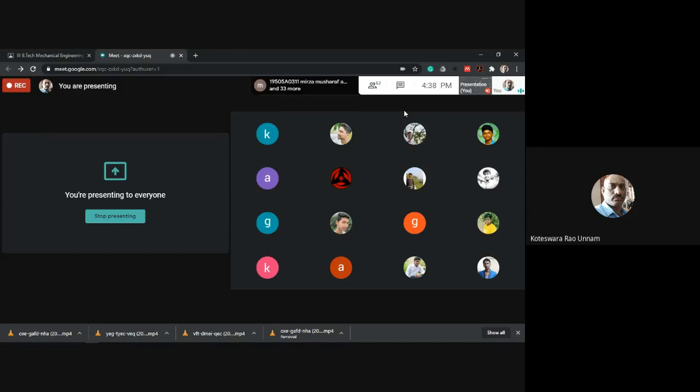Similarly, if I want to go for a butt joint having a specified efficiency, let us say 80%, then I can go for triple riveted equal width straps, or triple riveted unequal width straps also. So you need to first decide what type of joint you need to use. Then, based on the joint, you need to design it, meaning you need to specify the different pitch values, the margin values, and the diameter of the rivets. Those things you need to define.